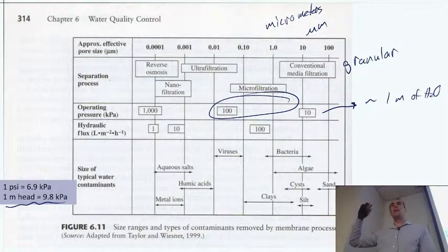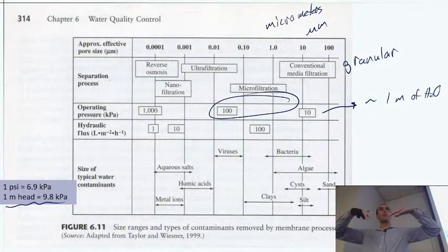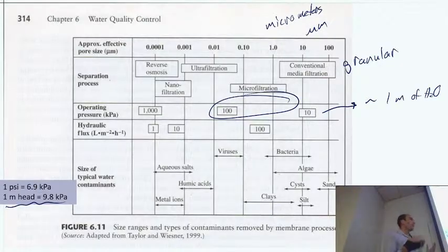You could see that maybe somebody could stand on one of these sand filters and you'd have these little troughs maybe waist high or something, right? You could kind of get a feel for the fact that water was going to stack up on top of them, but not tens and tens of meters, right? It's a couple meters maybe. So hopefully you can see how that's tracking.